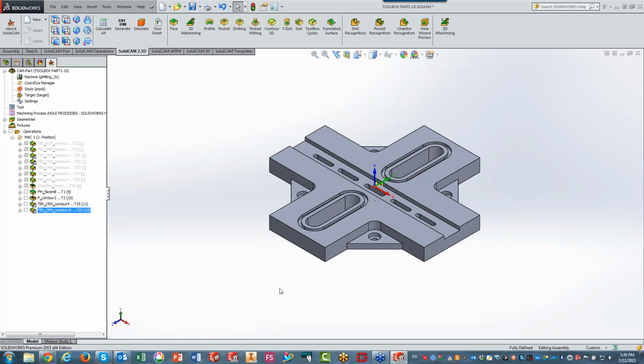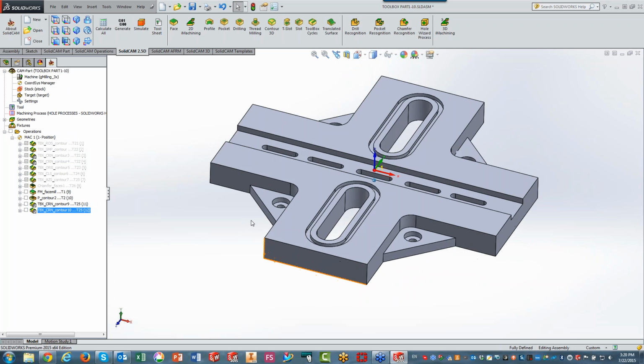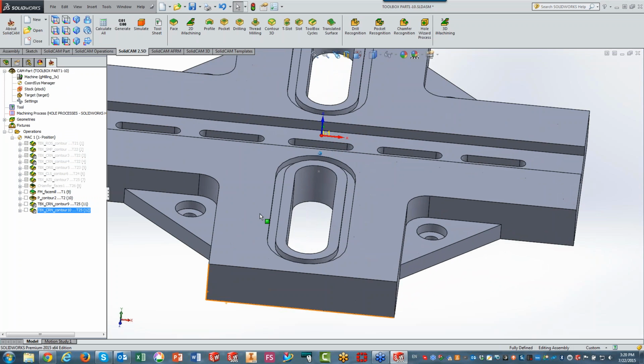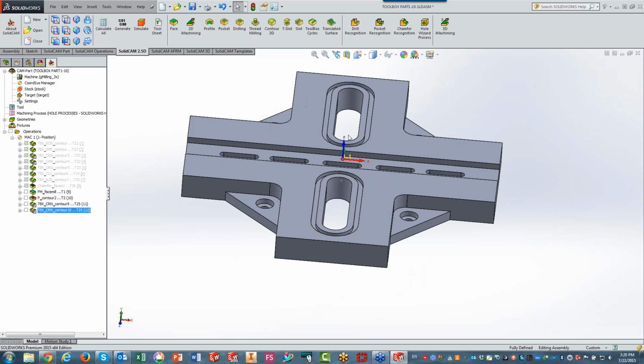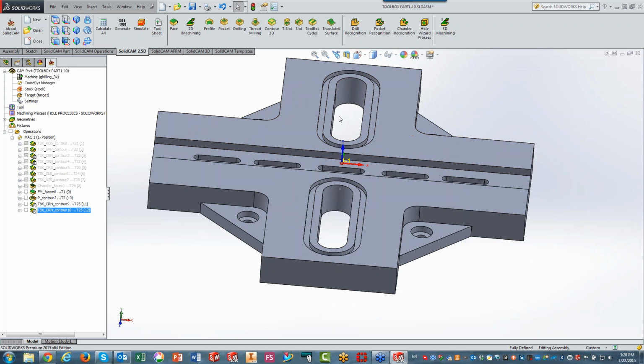And what I'd like to do next is to machine out these areas over here. Now, this is an area for an O-ring. Okay? You can see that's equally spaced all around. The slot is equally spaced all around. And again, I also have this on this side as well as that side, so it's a rotate of 180 degrees. So we know that already, excuse me.